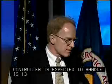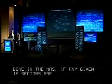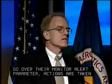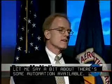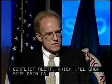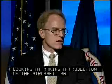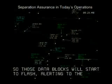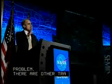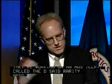So one of the things that is done in the NAS, if sectors are predicted to go over their monitor alert parameter, actions are taken to either divert aircraft or route them around the sectors. Let me just say a bit about some automation available. Conflict alert, which I'll show some data on later, is a legacy automation function that makes a projection of the aircraft trajectory based on 2 or 3 track hits. So if any of those aircraft are predicted to lose separation within 2 or 3 minutes, those data blocks will start flashing, alerting the controller to the potential problem. There are other trajectory-based automation systems that have been developed and are working in the NAS. They're not working on the radar controller's display. They're working on an auxiliary position, called the D-side radar associate position, that makes use of higher technology or trajectories.